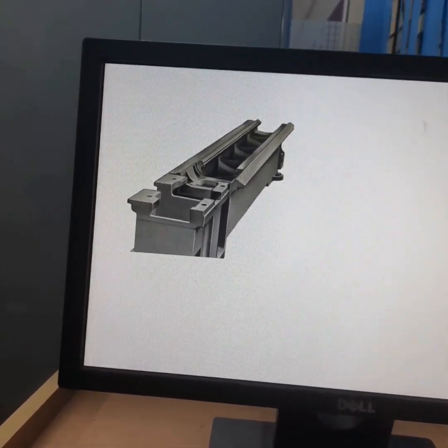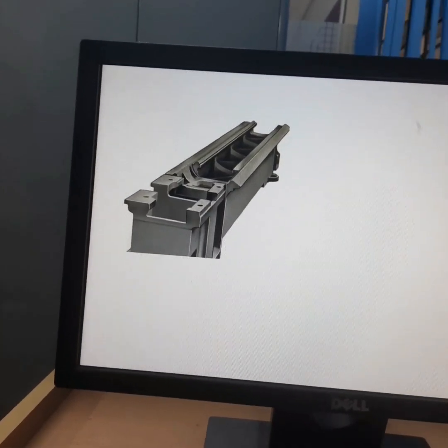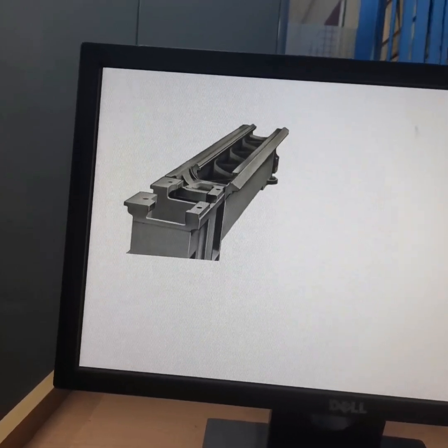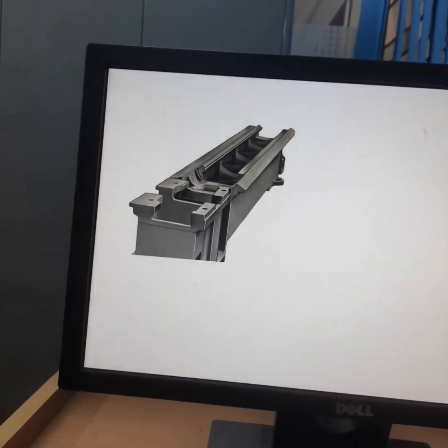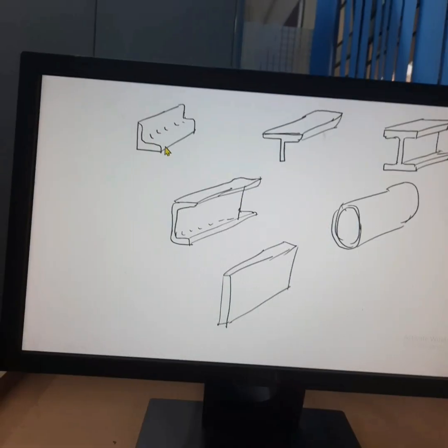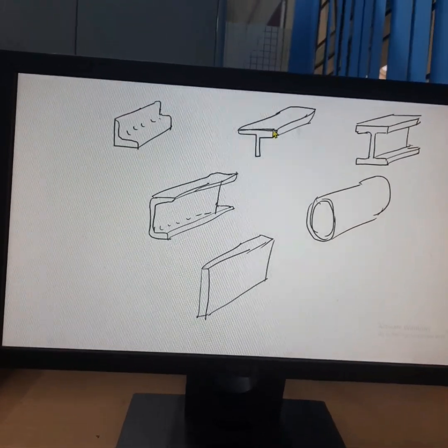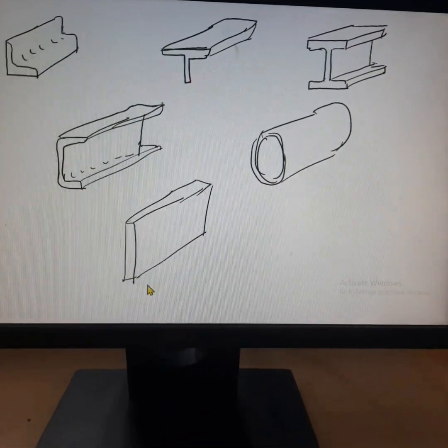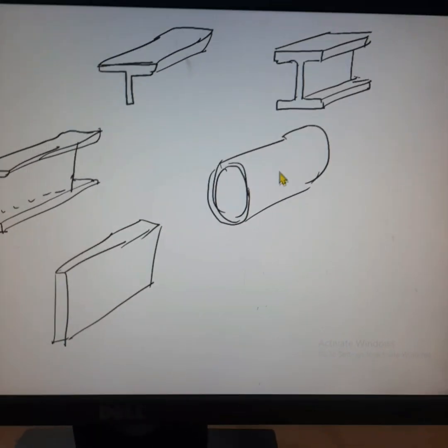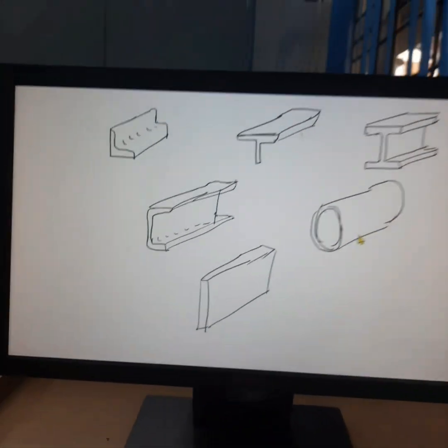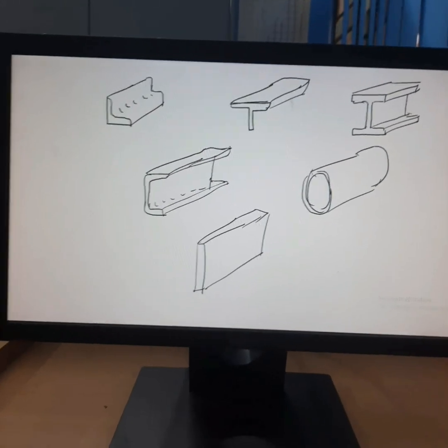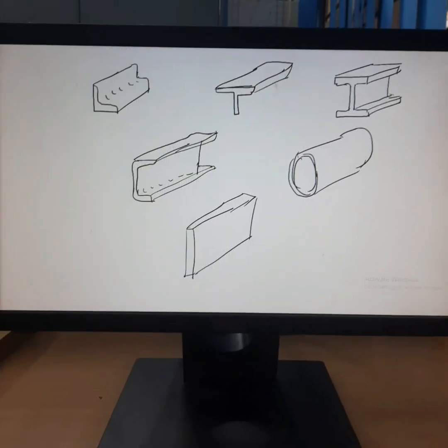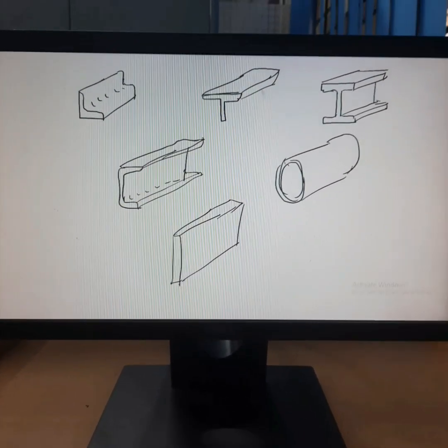So we can manufacture the lathe bed using standard structural components like plate, channels, I-beam, and join them using welding, of required size: T angle, I-beam, C channel, plates of various thicknesses, tubes of various sizes and thicknesses. So using these standard structures available in the market, we can fabricate a machine tool bed by joining them using welding.